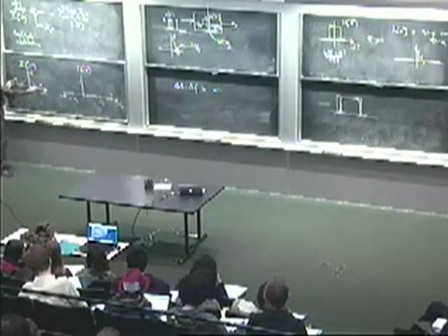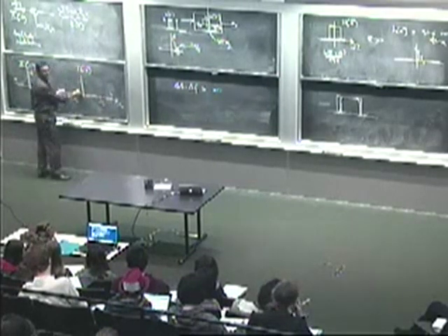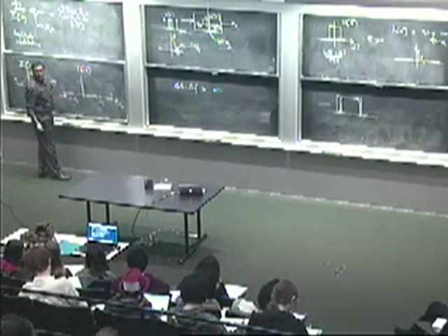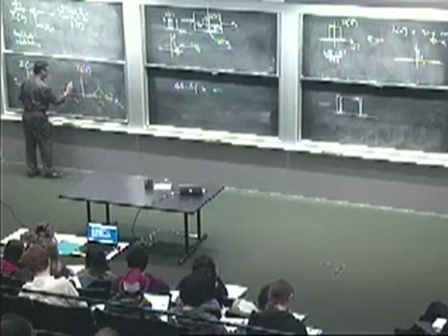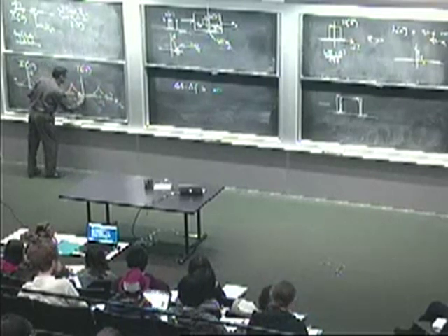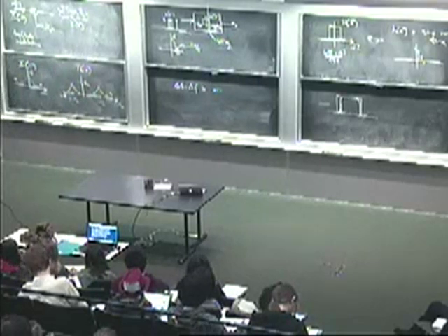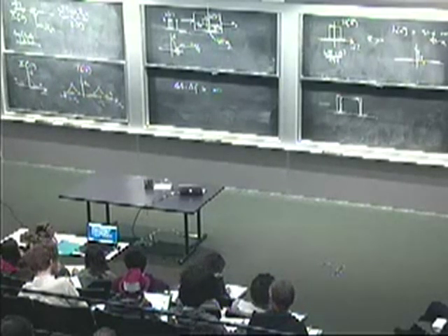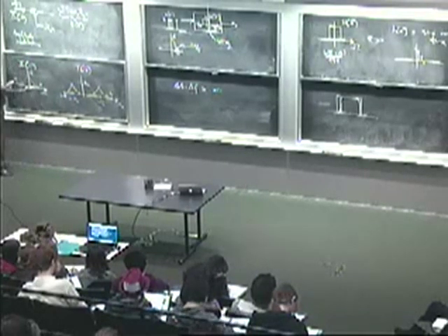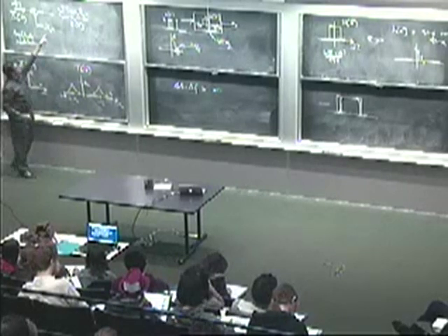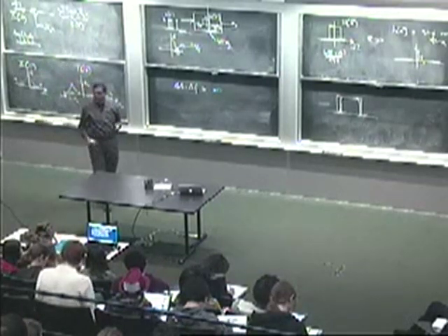Okay, so the prescription is simple. Take the spectral characteristic and replicate it at omega c and replicate it at minus omega c and scale by a half. So what you're going to get is this characteristic here, this characteristic here, and the height will be N/2. It's that simple. So you can go through the math. When you're done with the math, what it says is that the spectral characteristic of this modulated signal is the spectral characteristic of the envelope, the baseband signal, but translated to the position of the carrier.